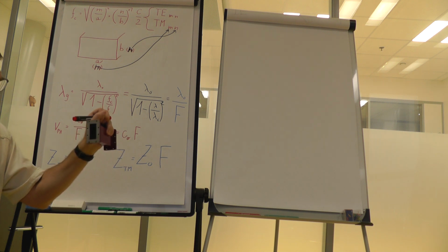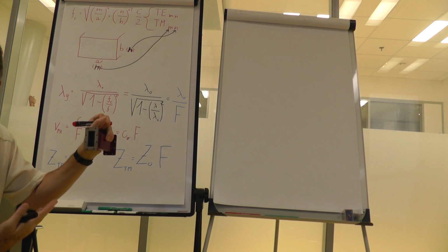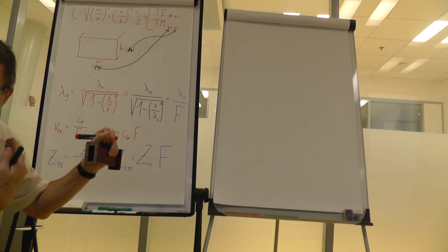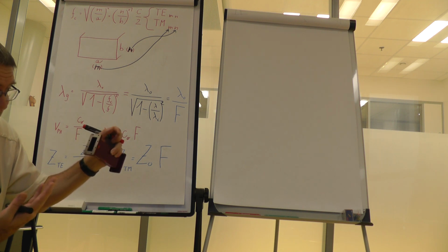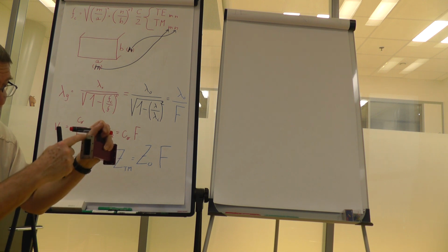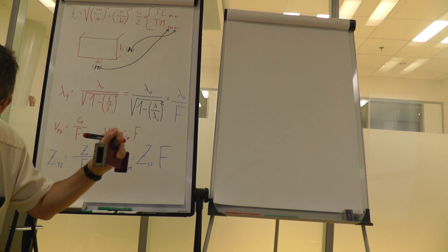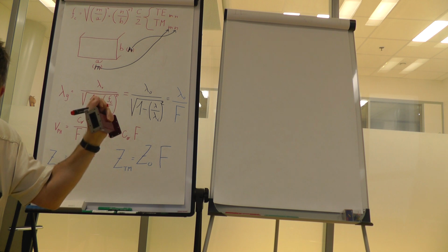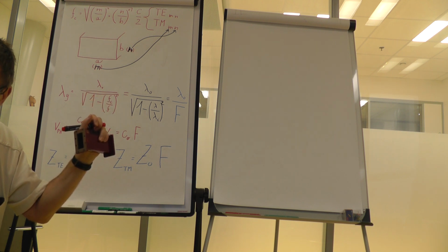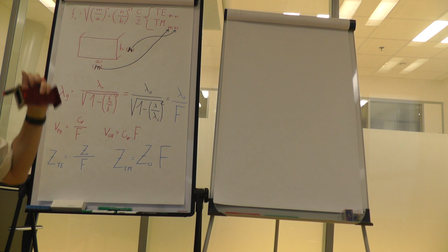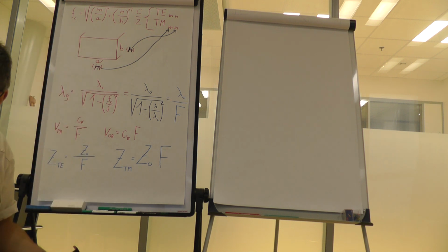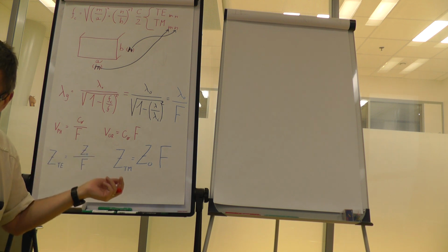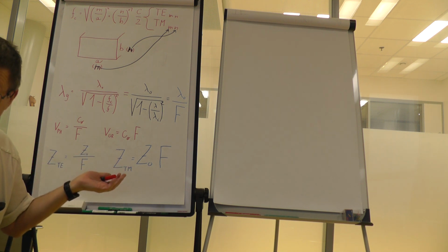Our everyday life says, well, okay, there is only one conductor that cannot propagate, but what we think in is the world of direct current. And for DC, the waveguide is not useful because you can't have two conductors. Here there is only one conductor. DC needs two conductors for propagation. But at higher frequencies, beginning from the critical frequency, you can use the waveguide to propagate energy or information.